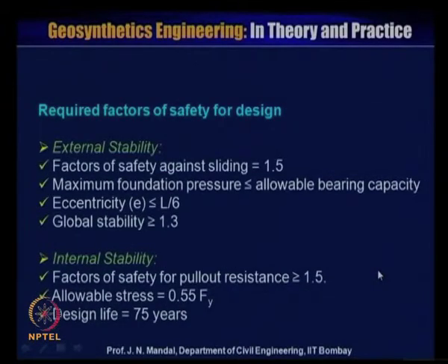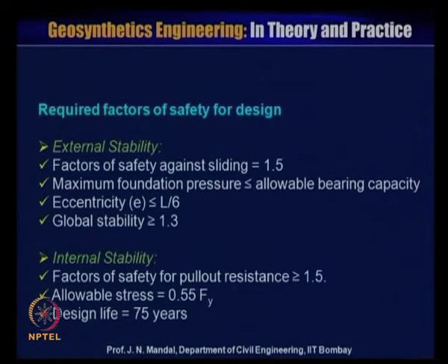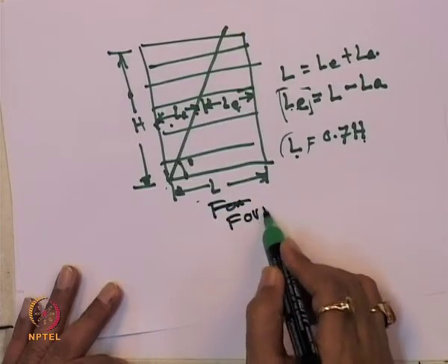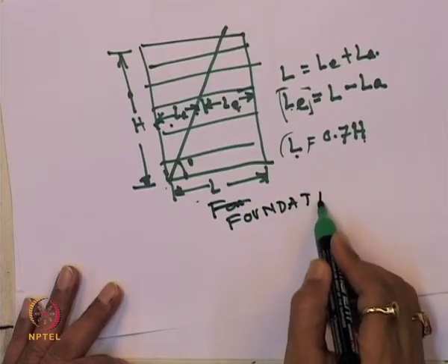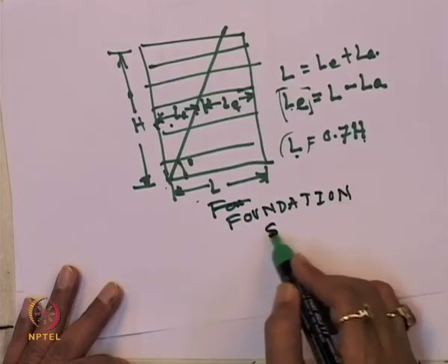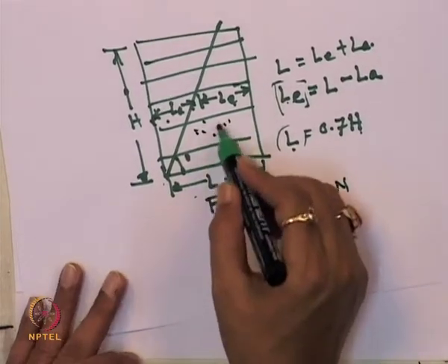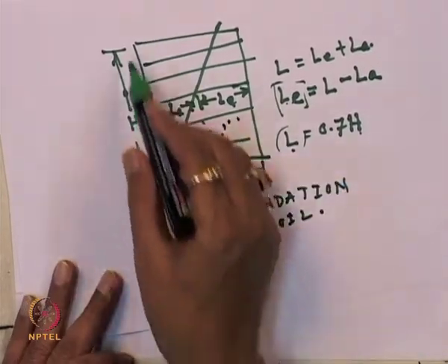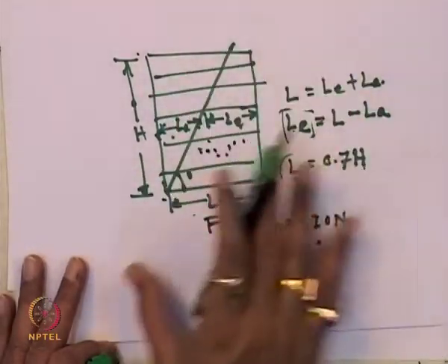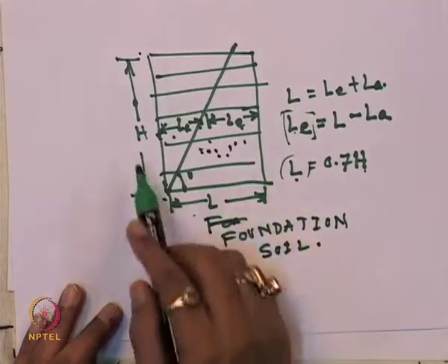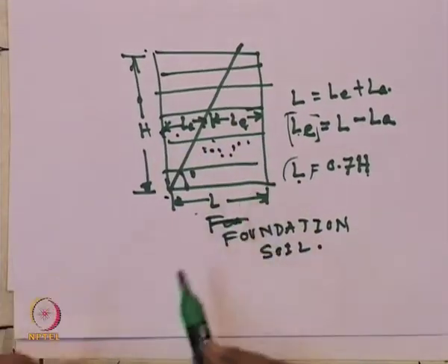So if I can show, if this is the foundation soil, you should know the properties of the foundation soil. You should know the properties of the retained soil. You should know the height. These are the properties given for the design of the reinforced soil wall.